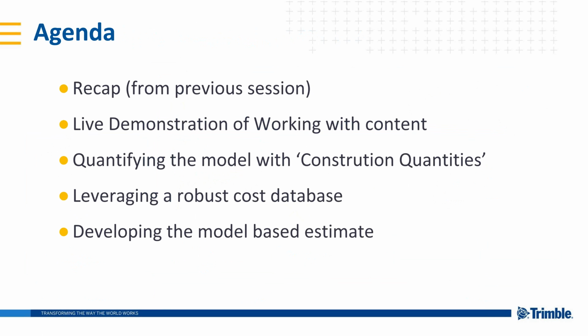So I want to just run through the agenda and let you know what I'm going to show you. We're going to jump right into the content, working with models, understanding them, kind of how do we analyze them. As estimators, we need to be comfortable with the documents first and foremost and understand the project. Then we will look at how we quantify the model in order to produce construction quantities. We're not talking about CAD quantity, we're talking about construction quantities, quantities that we would actually either build the job or estimate or schedule with.